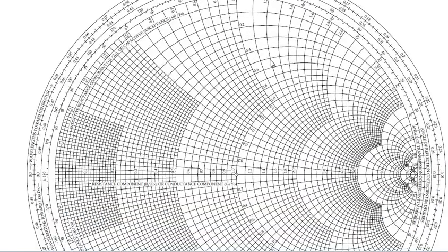See, in this case you already saw these concentric circles, which we call the resistive component. Concentric circles for resistive components, R by Z0 is a normalized one, or conductance components G by Z0. This is the resistance, the real part. We are going to refer to this axis, the resistive part, as the real axis.